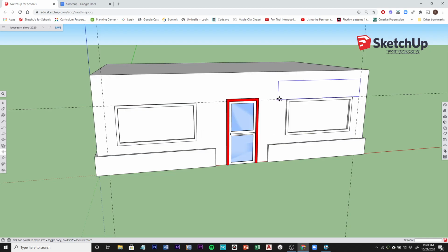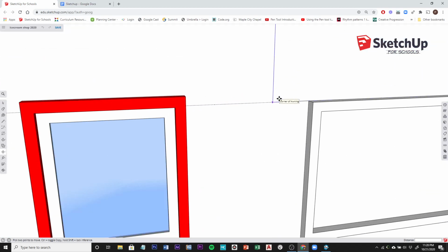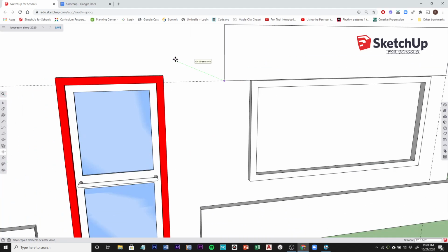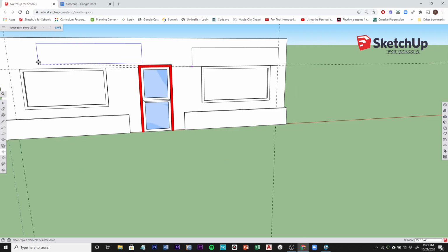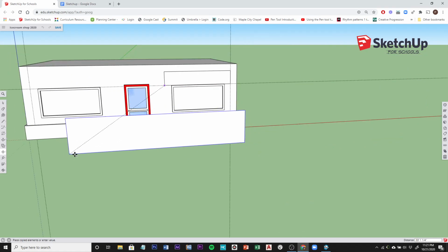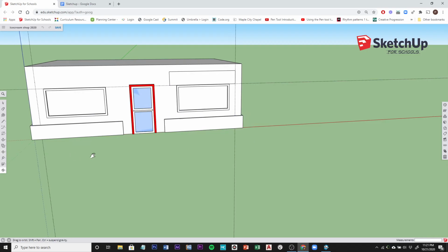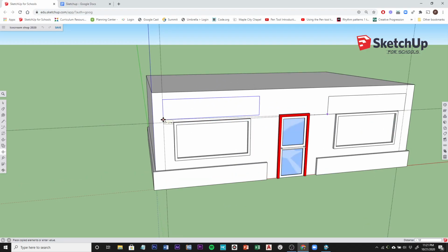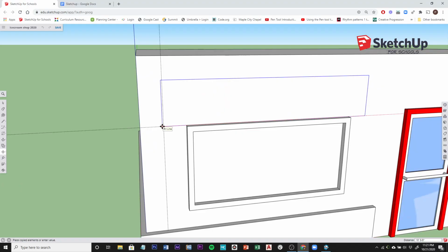Now we're going to go back to our rectangle, which is actually a component. I'm going to click in the lower left hand corner, right at the corner. Now I've made a copy, and if you need to, you can scroll, you can zoom out, you can also pan while you're doing the copy by holding the Shift key down and then clicking on the click wheel. Not a problem. And then zoom in where you want to place it to make sure you get right where that intersection point is.